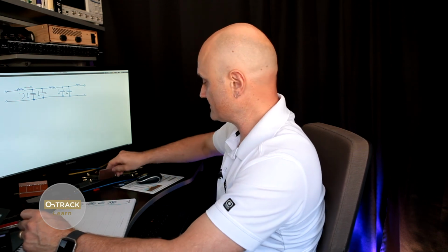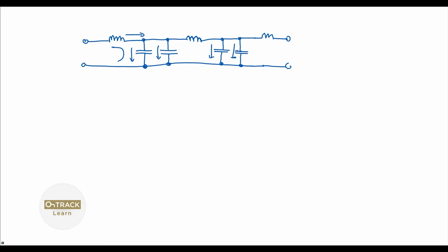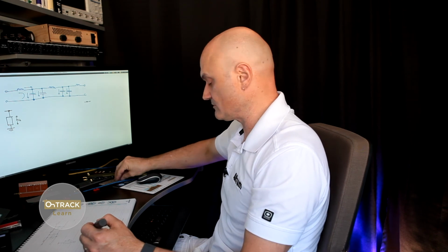So this has capacitance to the ground plane, but it also has inductance in its length. And so what does that mean? It means if you have a transmission line segment going to ground, say, and the electrical length of that is a quarter wavelength, then this is a resonance circuit. And similarly, like these here where they resonate, there's a notch frequency response we saw earlier.